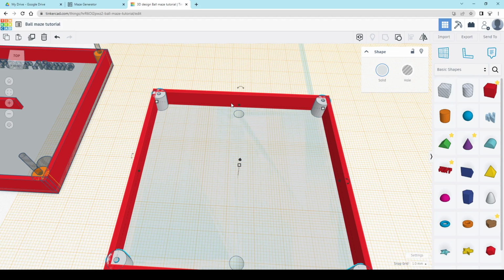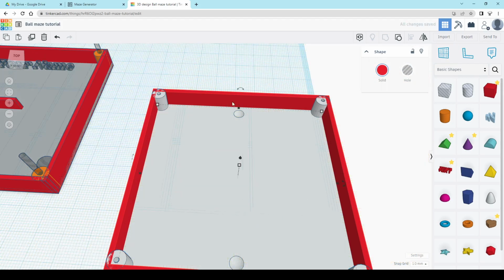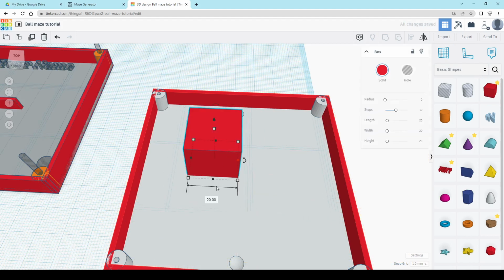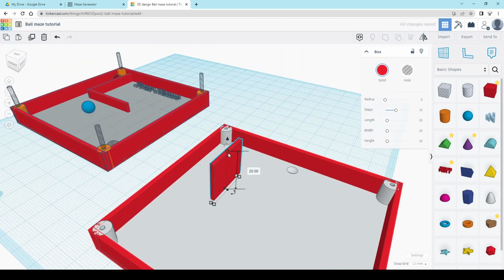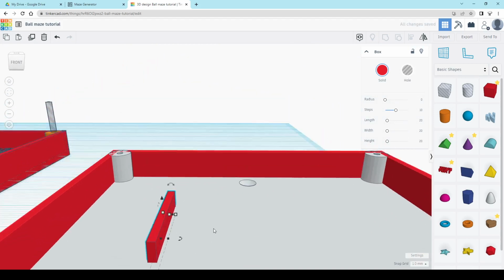To do the walls, what you could have done, what would have been easier actually, was to reuse one of these side walls here, but it's very easy to make it again. It's just a 1.5 width wall, and the height is, well, you can choose. I mean, you could make it 6. It prints quicker if you don't go all the way to the top.